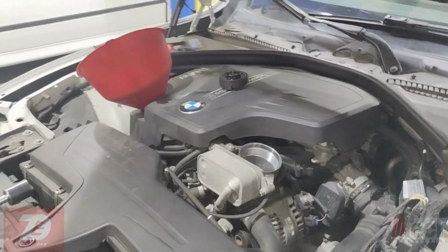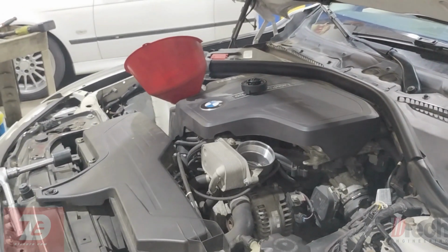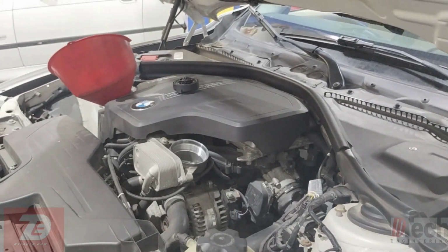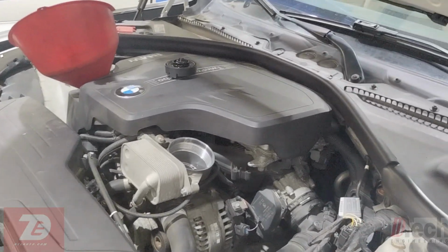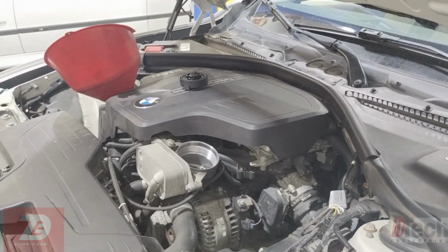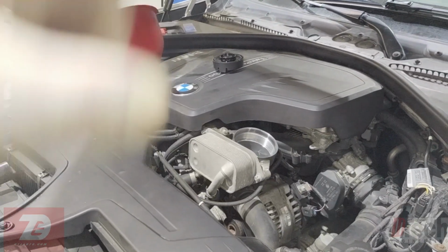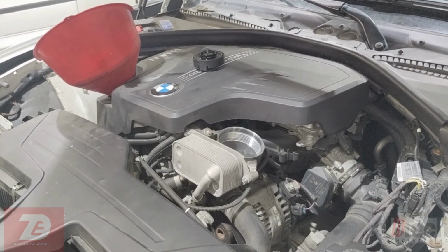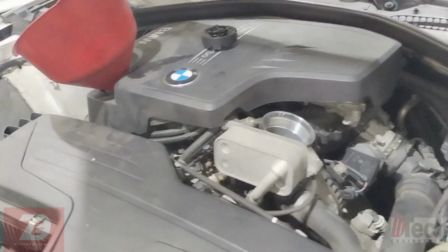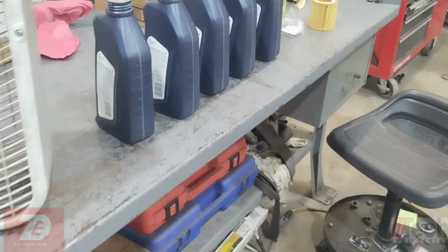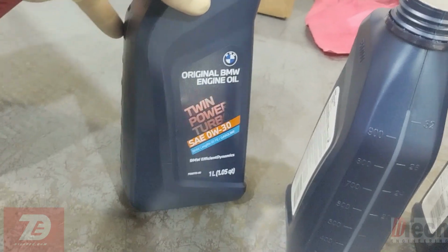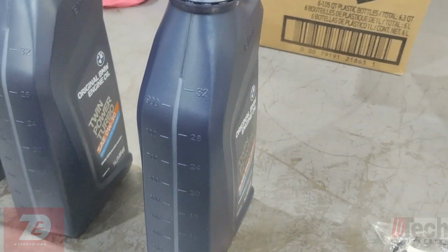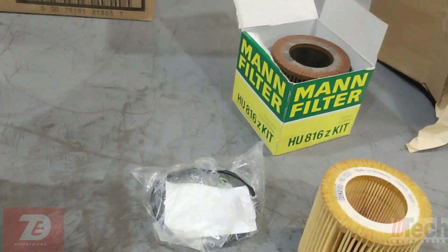Okay, so after seeing everything we did on the scope and how the oil pressure after some time dropped, of course, with some heat, I don't want to do anything crazy or drastic as far as making some sort of heavy work call. I opted to basically drop the oil. I looked at it, it didn't look crazy, but I'm going to go ahead and start off with the correct amount with the factory oil and see if that changes.